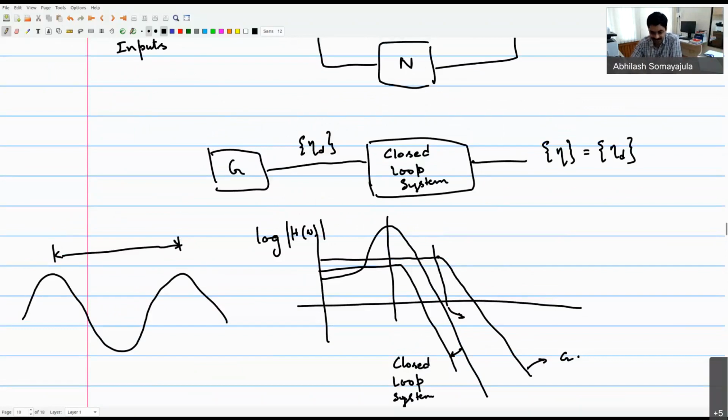But as far as linear systems are concerned, I can simply look at their transfer functions, figure out the bandwidth, and say that, okay, as long as the bandwidth of the craft is more than the bandwidth of my guidance system, then the guidance system is doing a good job. It can generate trajectories which can typically be followed by my craft. Okay.